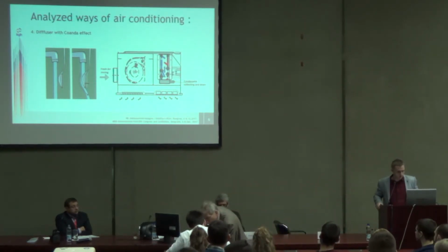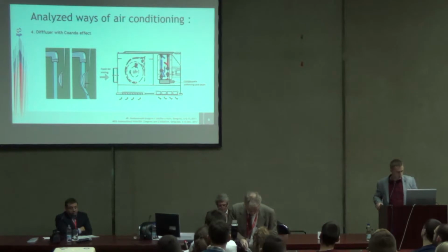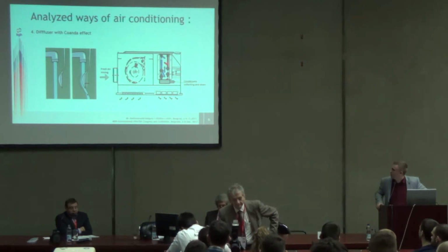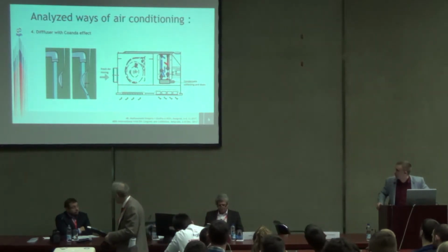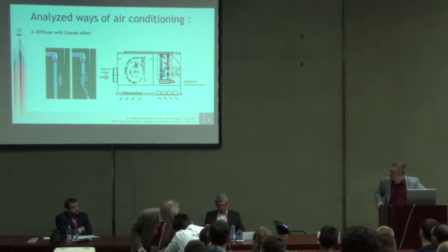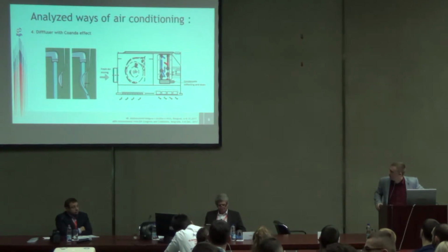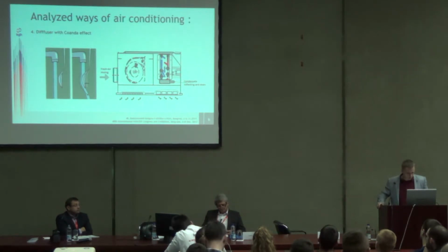We can find commercial fan coil units which use the Coanda effect to distribute the air in rooms. Like a classical fan coil unit, it consists of a fan, a fresh air inlet, the heat exchangers, and condensate collecting and drain. The most important part are the Coanda diffusers, which make the air enter the room parallel with the ceiling and give it high speed to continue to spread over the ceiling. The best implementation of the Coanda diffusers is in rooms with a big ceiling area, so the air can spread properly.